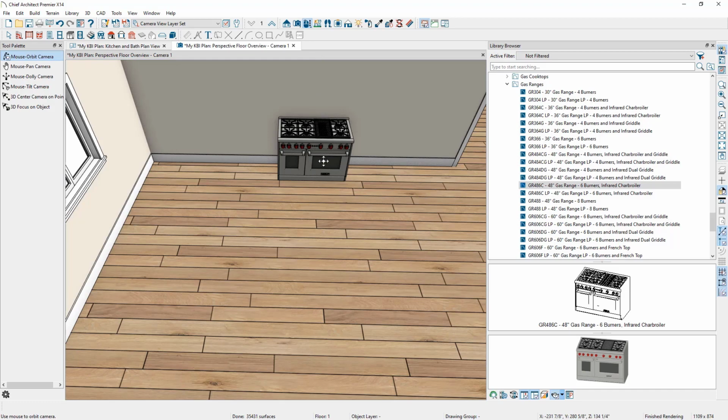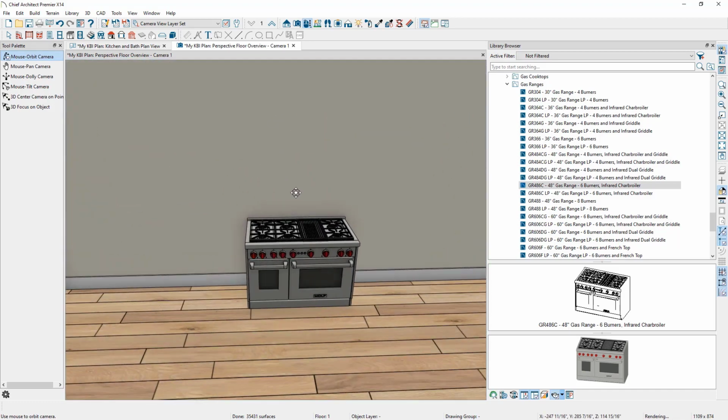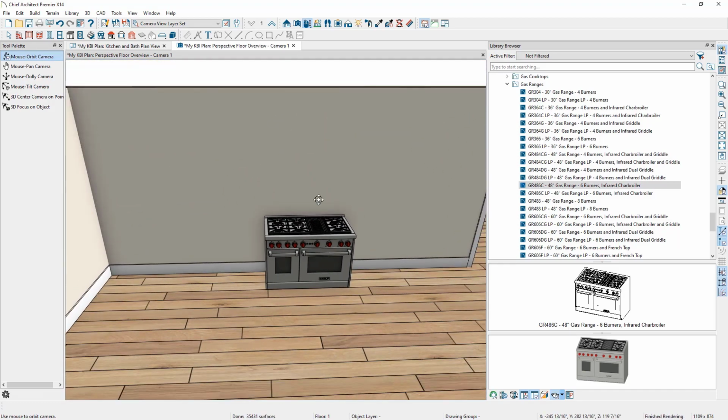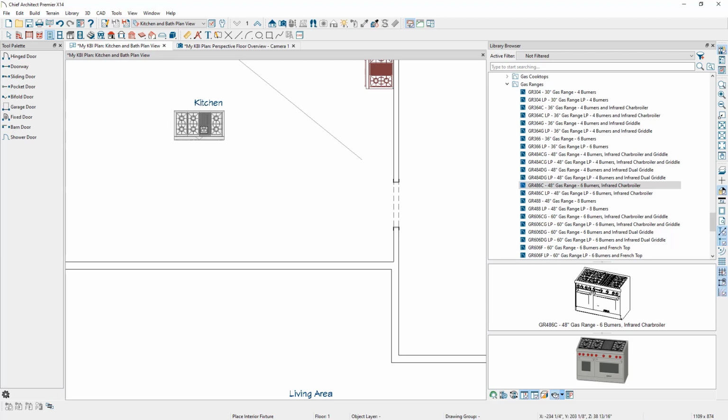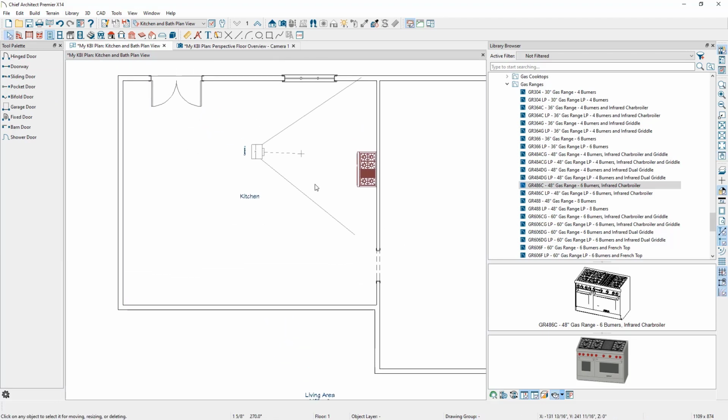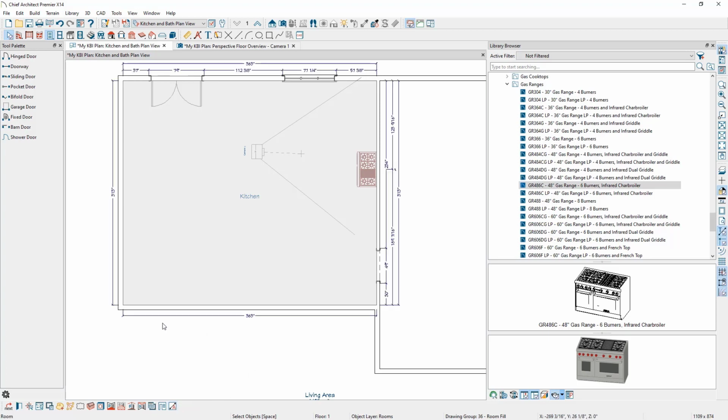Next, let's rotate our view slightly so it's a little bit easier to see, and let's zoom in. Then next, let's make sure we have this range positioned in this wall where we want it. To do this, let's jump back to the floor plan view. If I press spacebar, we can add more permanent dimensions going around this room that locate the room width, window casings, and objects like this range. If I click in this room, in the bottom toolbar, there's an option that says Auto Room Dimensions. When I click on it, you can see how it adds those dimensions going throughout the space.